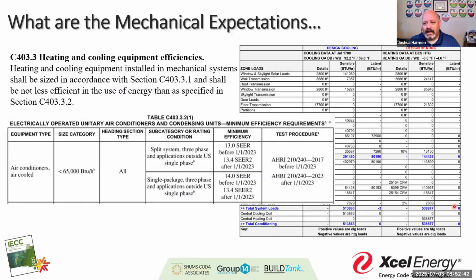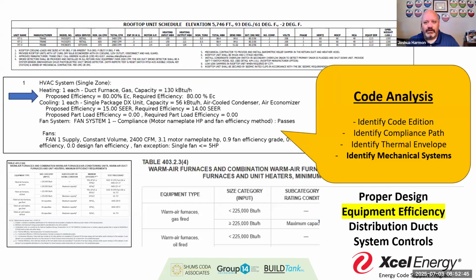And then after I've evaluated that design, then I get into the equipment selection, right? A lot of times I see this in a comp check. If I don't see it in a comp check, I usually have to remind contractors the first couple times. I need to see that equipment efficiency rating, right? Or provide me the details. If I have to, but again, remember, I'm billing you by the hour. And so I'm billing you to look through 15 pages of Trane documents to figure out what's the efficiency rating for this specific size unit in this specific configuration. I can do it. It's going to cost, right?